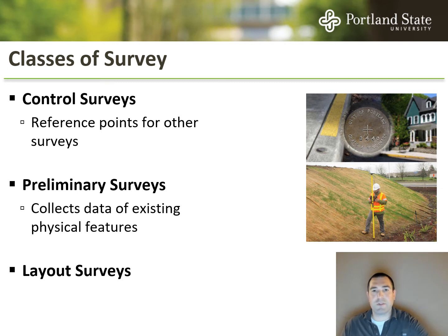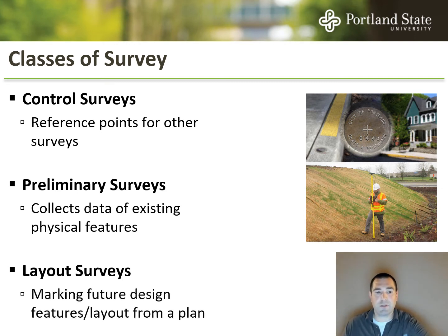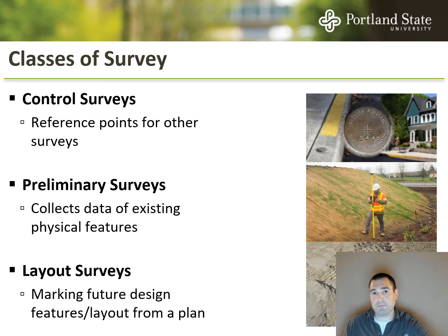And then layout surveys, this would be that construction service that we talked about, where the design is completed. Then the surveyor would go out with the plan set. They would put oftentimes stakes like this to either help with grading of the site or to identify the corners of foundations, the locations of utilities, things like that. And nowadays you actually can see a lot of GPS at this point as well too.